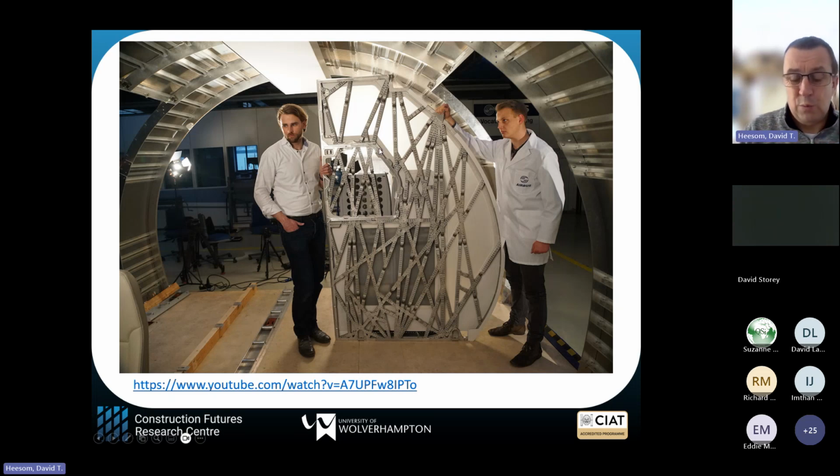There were a couple more examples. There was one with a motorbike, where they said, these are the stresses and strains on the motorbike, but can you redesign the frame for us and optimize it for materials and weight reduction? In this example, it redesigned it so it was structurally sound, but it used a hell of a lot less material, which gave this quite odd-looking design. But it optimized it. The computer generated it. It was generative design, and it went through thousands and thousands of solutions to get to this.